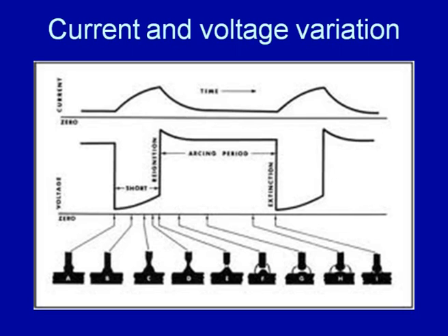This minor increase in the voltage is occurring because of the thinning and the reduction in the section of the molten metal drop in the process of detachment. Once the gap is created, the full open circuit voltage is established, and then on striking of the arc again, this voltage is stabilized.